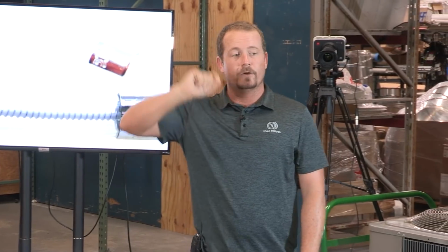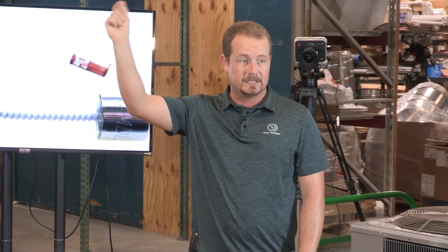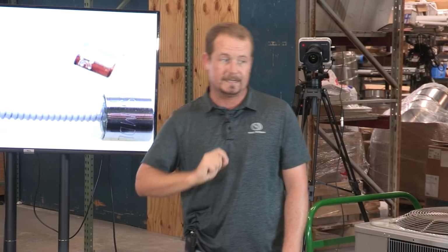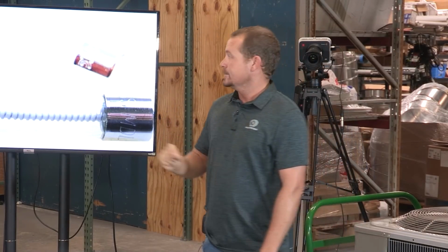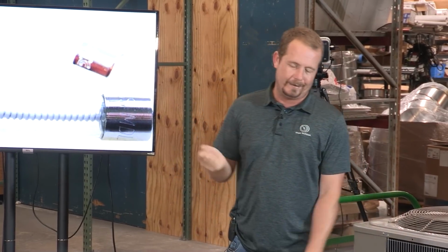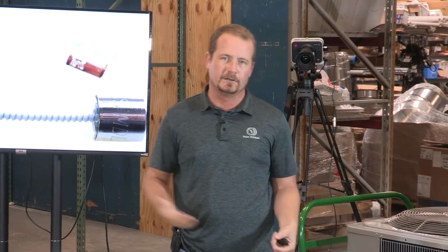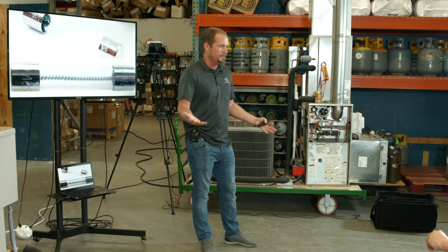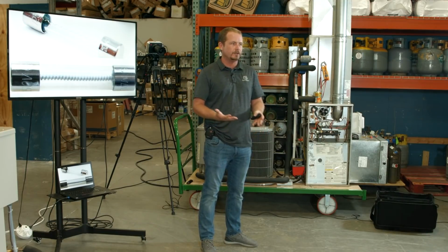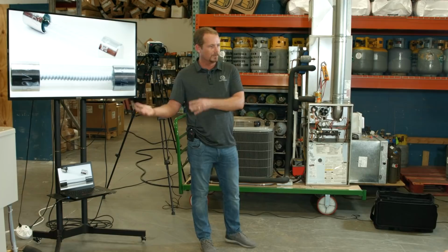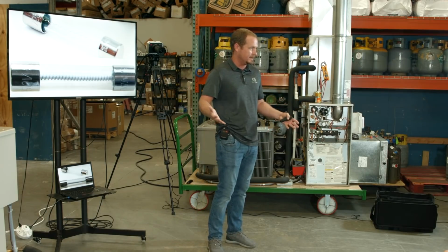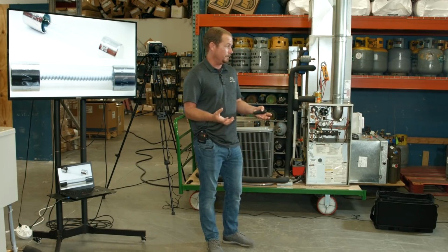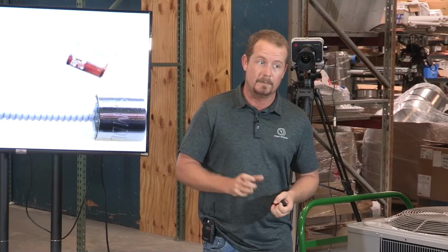So the amount of overcurrent dictates the speed that it's going to trip, right? But also the type of fuse dictates how quickly it's going to trip. On a fast blow fuse, I'm sure there's some rating out there, probably some table somewhere, that tells you exactly the amount of time based on the amount of overcurrent. We don't care. The main thing you need to know is that you don't want to replace a slow blow with a fast blow, or a fast blow with a slow blow, because they do different things. The fast blow needs to protect electronics, for example. You don't want it to run even a short period of time at overcurrent.